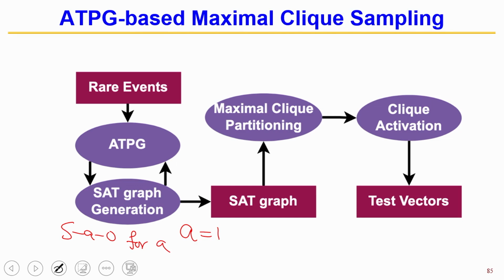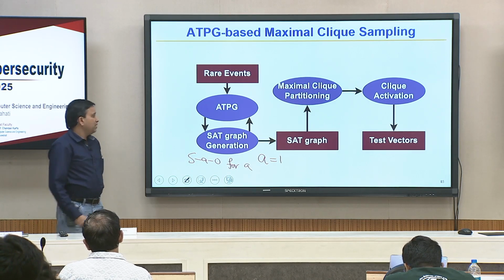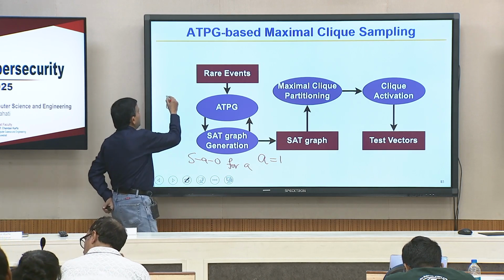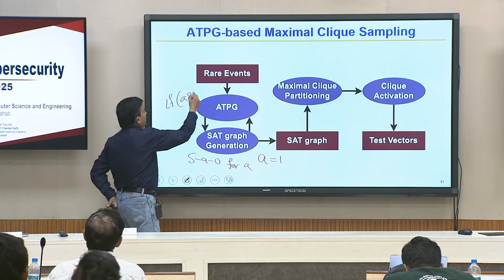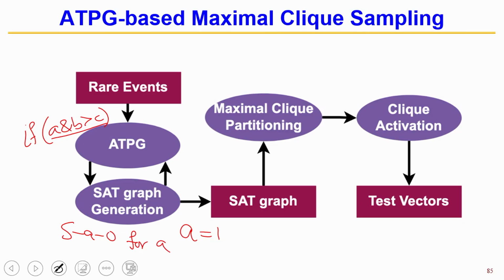Because ATPG does not understand anything other than stuck at 0 and stuck at 1, and because it is Boolean, it is much easier. If it was something else, in the decimal domain, it might be a little more difficult, but it is basically as trivial as this. Same thing for branch coverage, because a branch could be very complicated. Your branch, if A and B greater than C or whatever it is, is nothing but a condition. We create a variable x, give it that condition,